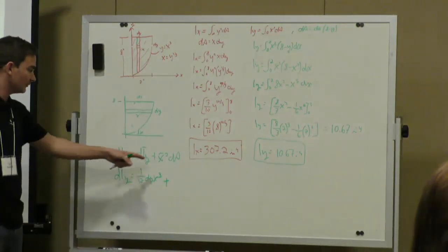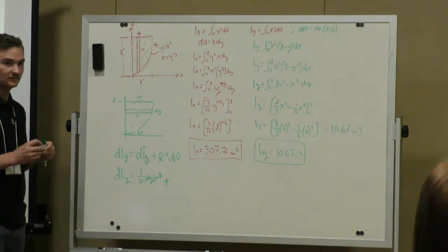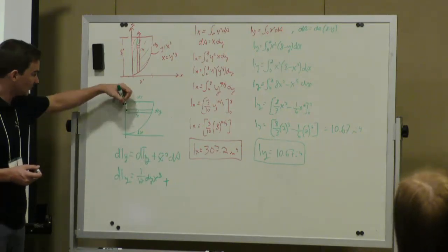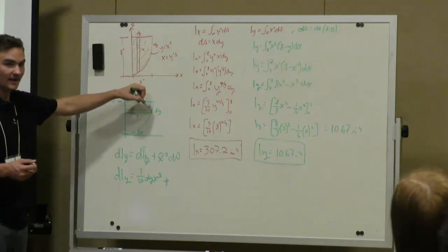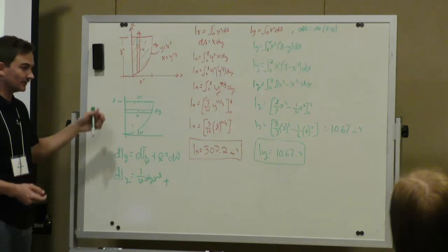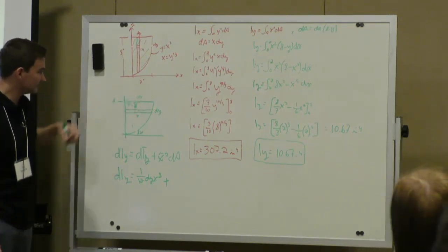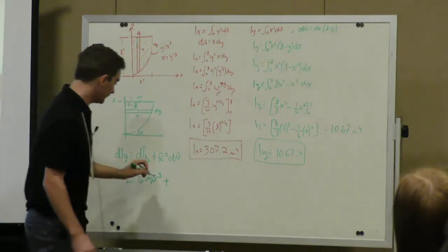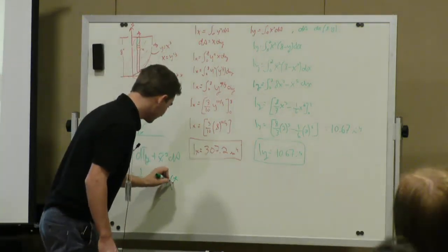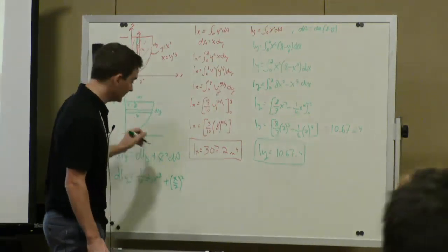Now, what is our x tilde in this case? 1/2 x. Yeah. If our total length is x, the centroid for a rectangle is just half of the height, so our x tilde is just x divided by 2. Then we would plug in x over 2 squared, and our differential area is x dy.